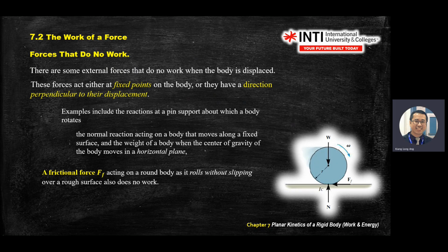This is work. It does not mean there is no friction at the wheel. It does not mean there is no friction force when the wheel touches the ground. They still have friction, but that friction does not do work. I need to highlight that one. Don't say, hey sir, I don't need to calculate it, then wrong. You still need to calculate the friction force.